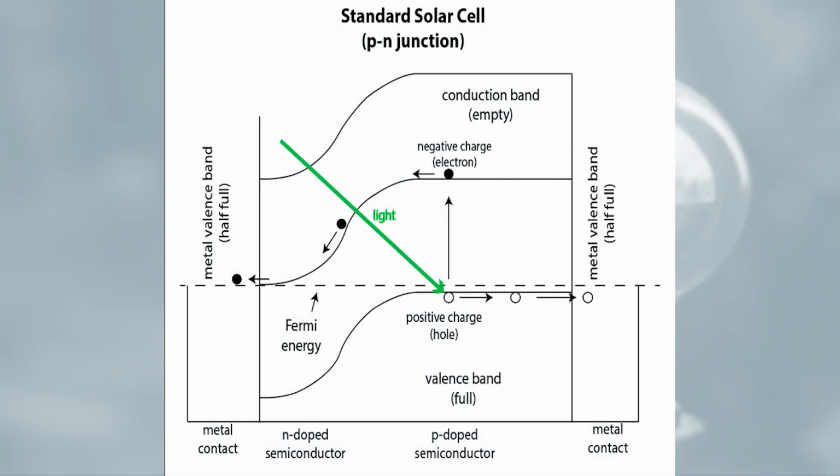When sunlight falls on a semiconductor p-n junction, electrons within the crystal lattice may be freed, creating an electron-hole pair. These free carrier pairs are separated by the p-n junction and contribute to electric current. Only photons with a certain level of energy are able to free electrons in semiconductor material from their atomic bonds to produce an electric current.